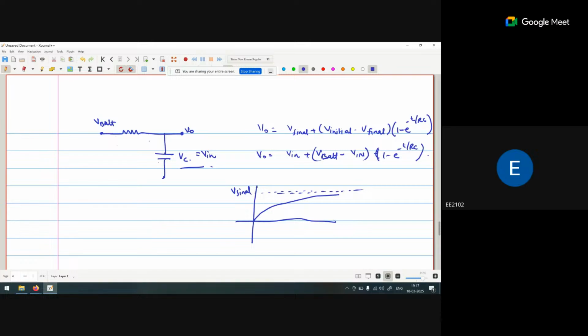If my capacitor will hold the charge up to 20 or 24 hours, I can use that capacitor as my battery. But if the capacitor is charged in 1 minute and discharged in half a minute or 2 minutes, I can't use that capacitor for battery purposes. So this will be dependent on the RC time constant.